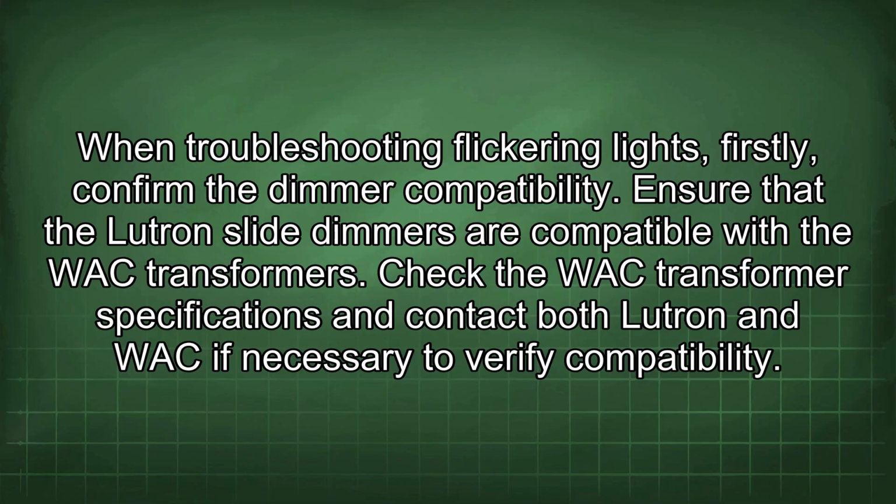When troubleshooting flickering lights, firstly, confirm the dimmer compatibility. Ensure that the Lutron slide dimmers are compatible with the WAC transformers. Check the WAC transformer specifications and contact both Lutron and WAC if necessary to verify compatibility.